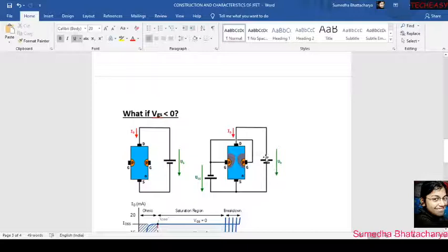But after connecting the VDD, when the current tries to pass through the N channel, the current will see that the depletion region is already created, and with the help of VDD the depletion region will also increase, but the pinch off voltage will come shortly.